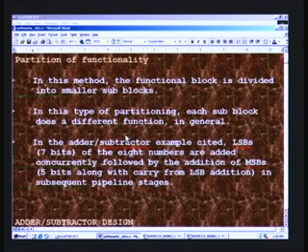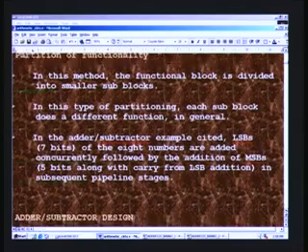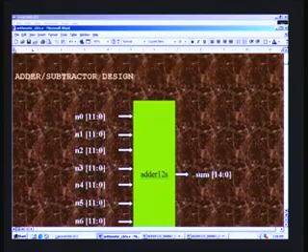When the second clock pulse arrives, we take the carry of this LSB addition and then add it with the MSBs. So MSB in this case will be 5 bits, and that is why we say 5 bits along with carry from LSB addition in subsequent pipeline stages. And so the adder subtractor design is as follows.